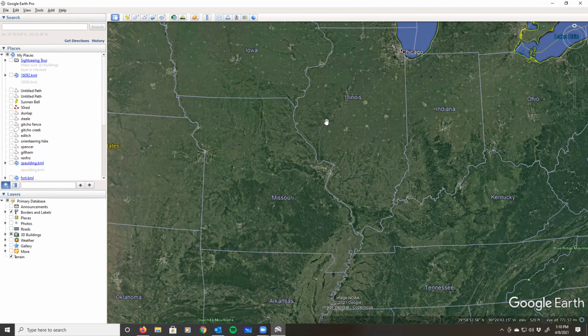What that allows for is that when you reach 1/6 in from the eastern edge of the projection area, you're pretty much at a scale factor of 1. Likewise, when you come 1/6 of the distance in from the western edge of the projection, you're at a scale factor of 1 there as well.